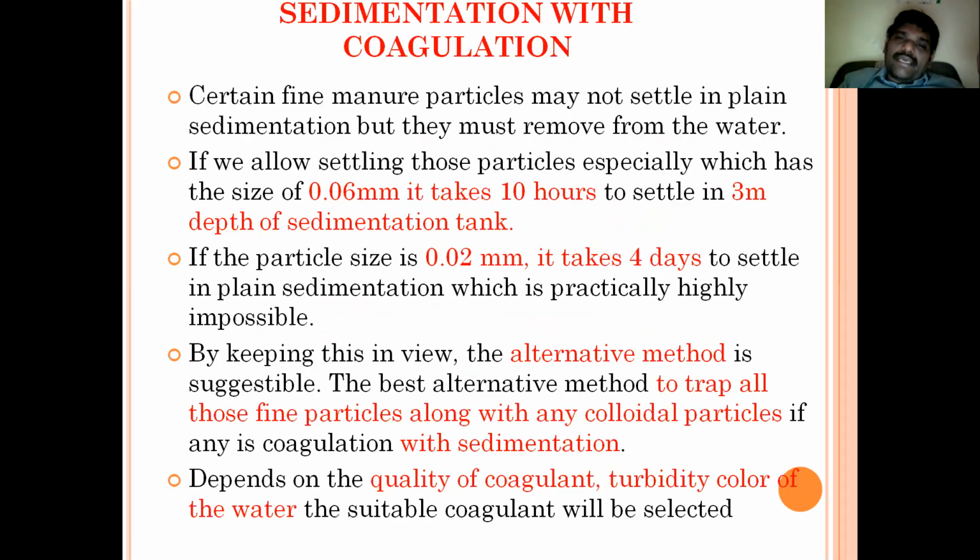Now the topic is sedimentation with coagulation. In the sedimentation part, actually we are not doing anything, we are just allowing water to stand without any disturbance. Based on gravity, all the heavy particles will settle at the bottom and will be taken off from there.